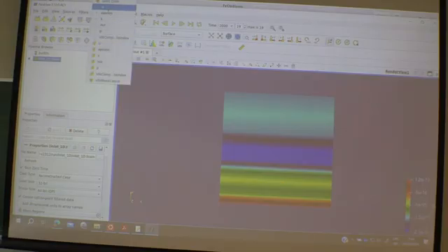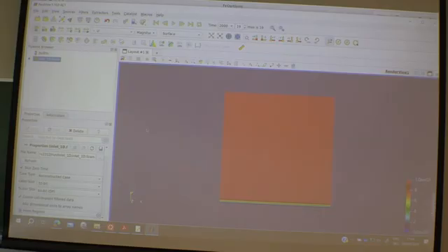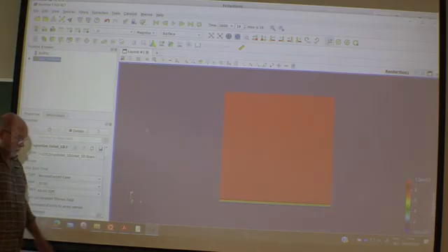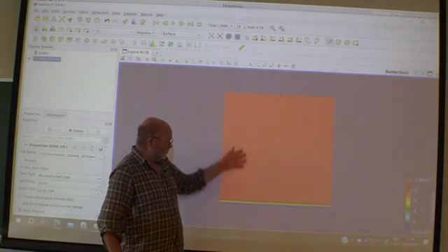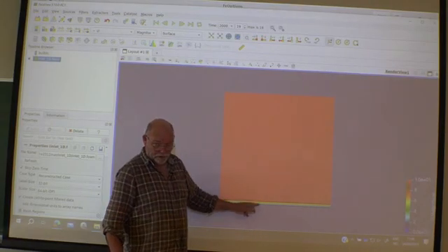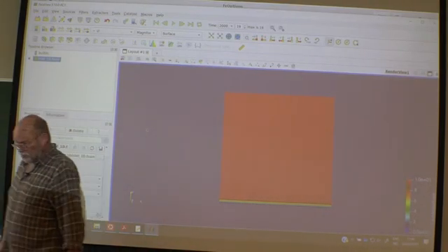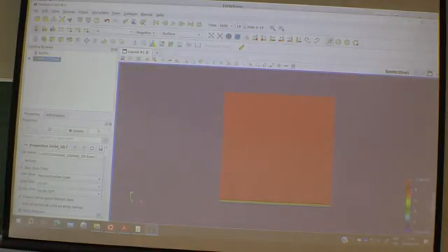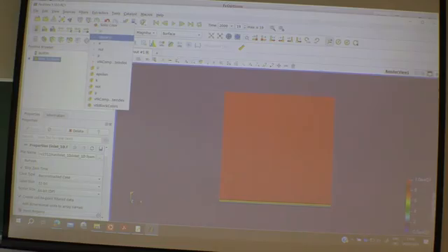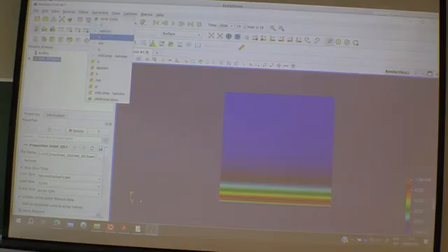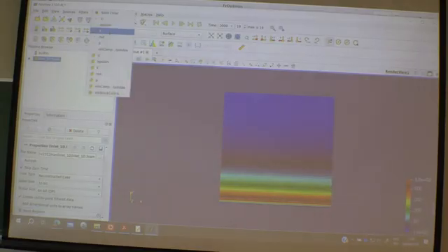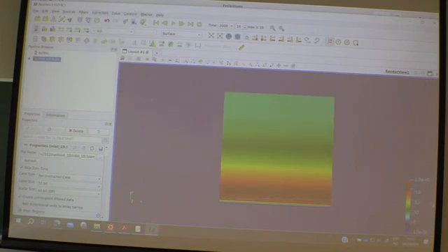For the velocity, then we have something that makes sense. We have a high velocity in most of the region, and then a sharp boundary layer down here. A little too sharp, maybe. And then, how about our epsilon, and k, and the eddy viscosity we have. So yes, this is one way you can produce one-dimensional results. But is it trustworthy? Well, actually not really.